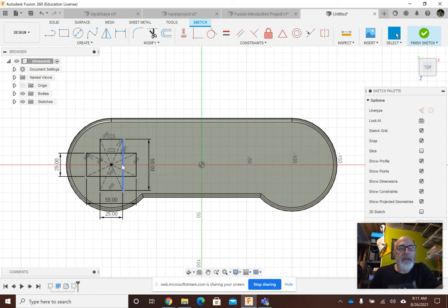To complete my design, I need to get rid of these interior lines. So let's go to the Modify, Trim tool. There's the shortcut, Trim. Click, and let's get rid of these interior lines. Look at that. My directional lines from the center rectangle are in the way. So let's get rid of each little section. Be very careful. If you happen to click on the wrong one and delete a line you shouldn't delete, you can undo. Only the purple section will delete.